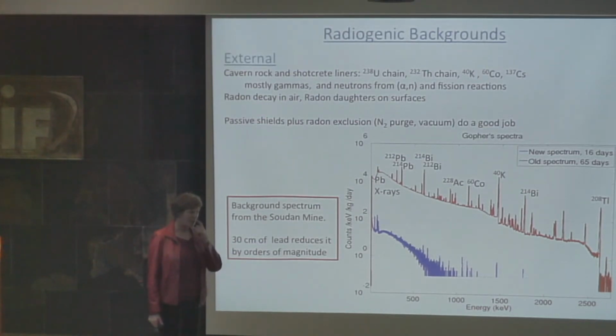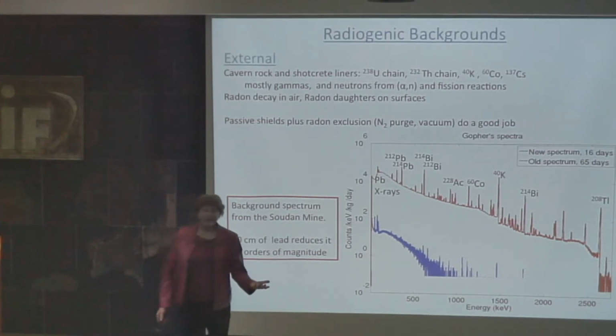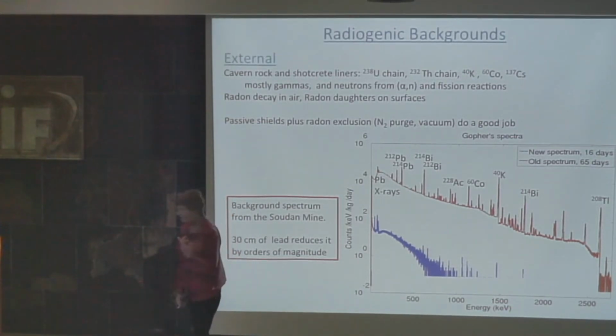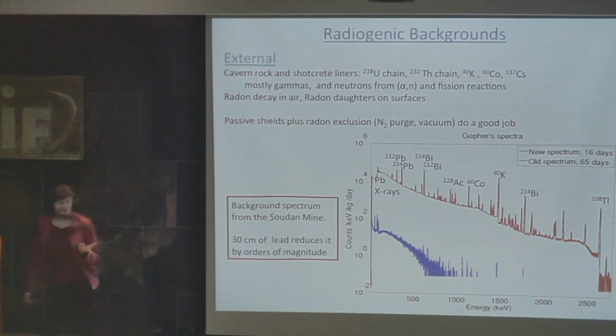It's interesting because in the old areas of the lab the shotcrete has a low amount of radioactivity, but the new areas are worse. You could see because we measured the gamma flux, and it is higher, like 50% higher, and it is the shotcrete. So it's not enough to just say the word shotcrete. It's going to depend on the vendor, it's going to depend on composition. Everything needs to go through some sort of assay. So you can see all of the kinds of cautions that we have to take for that.